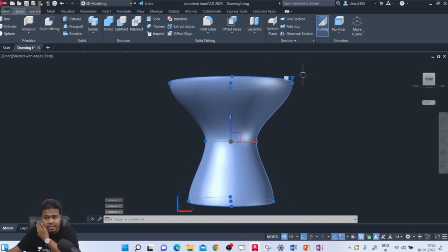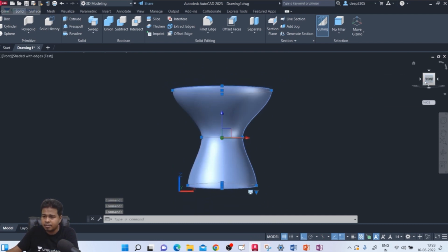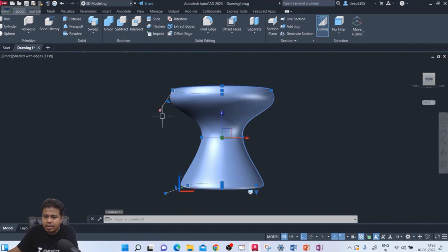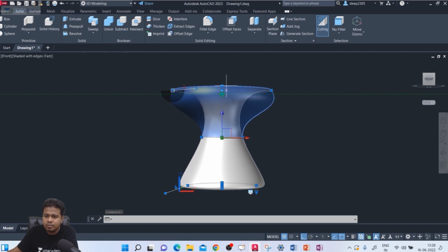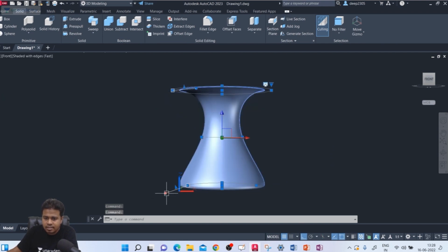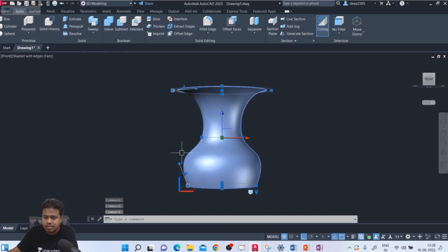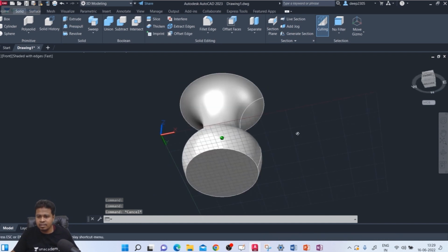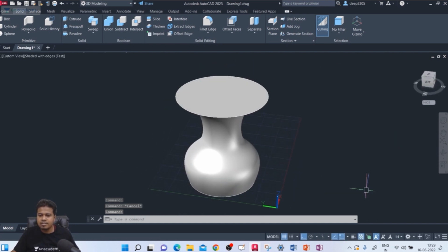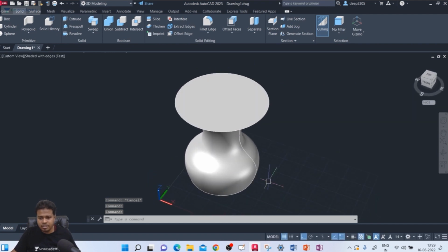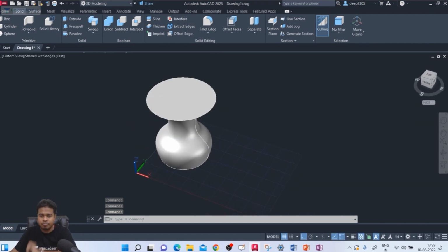As of now, I am seeing the front view. If you click onto that particular cube front view, you will see this. Now, if you go to draft angle, you can manage the angle apart from 90 degrees. Suppose you want some other angle, you can do that. So this is how it will look. I hope this is clear. So these are some more options of that loft using this particular arrow. I hope this is clear.